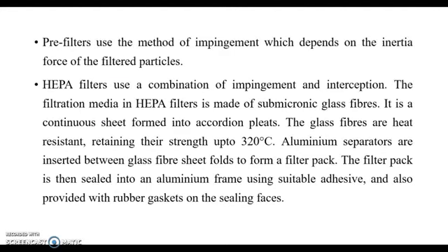Next, the pre-filters. The pre-filter uses the method of impingement. It largely depends on the inertial force of the filtered particle. The third filter is the HEPA filter. These filters use the principle of a combination of impingement and interception.